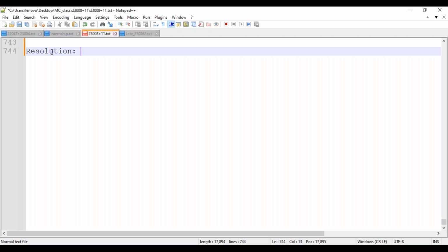Now here also, when it comes to the ADC block, the ADC is converting the analog value to a digital value. It converts an analog value and gives us a digital value. Now, don't you think I need a memory to store that digital value? Do I not need a special register to store that digital value? Yes. The width of the register I use to have the digital value stored is nothing but the resolution.